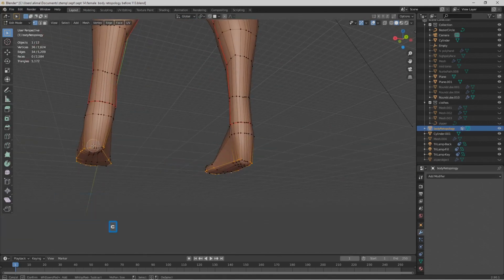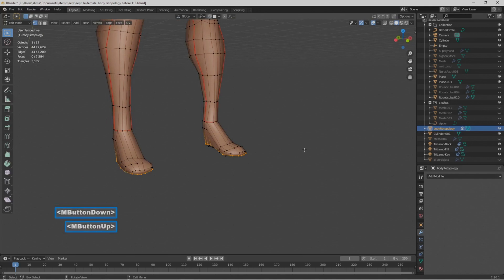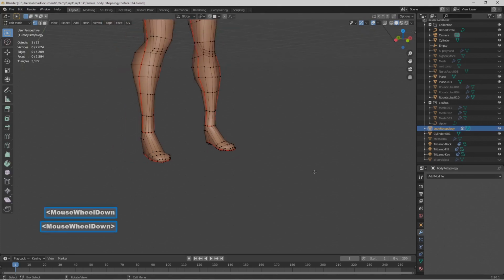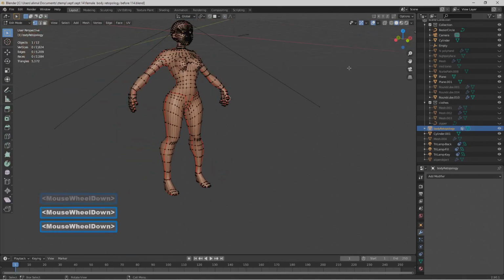I'm going to press C for Paint Select. I'll select there. I'll right click to get out of Paint Select. I'll hold Control, press E, then select Mark Seam. I'll hold Alt, press A to deselect. Okay, I'm going to zoom back, select the hand to pan.